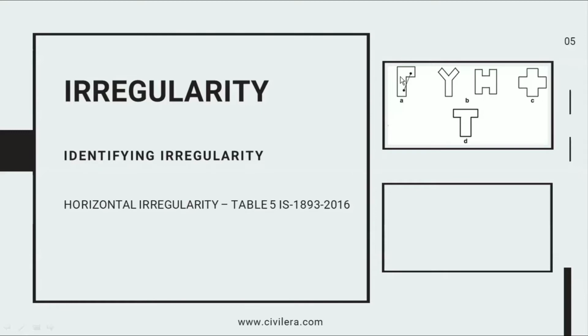When the ground moves, the inertia forces the building to stay in place, and this creates a kind of displacement in your building, and this displacement becomes a force in your building. This is how a lateral force is induced in a building due to earthquake. So these irregular shapes aren't good. These are not going to help the building when there is a ground movement.